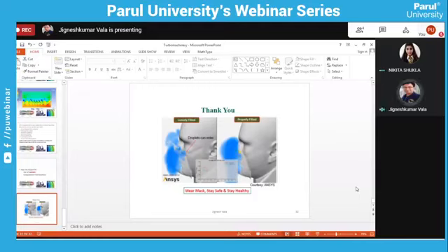Yes, very good question. Flow models: in computational fluid dynamics, there are different types of turbulence models, right? RSM, K epsilon, K omega, DNS, LES. There are different types of Reynolds turbulence models. In the turbomachinery field, many researchers conclude that K epsilon is a very appropriate model, for example in the case where we are doing the analysis of the cooling blade technique, right?